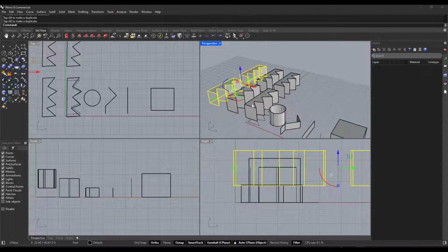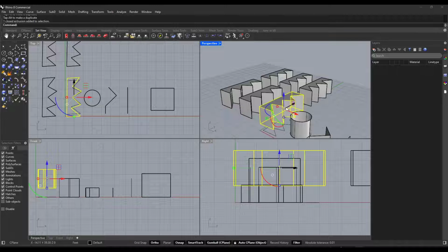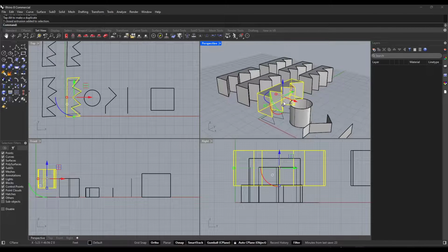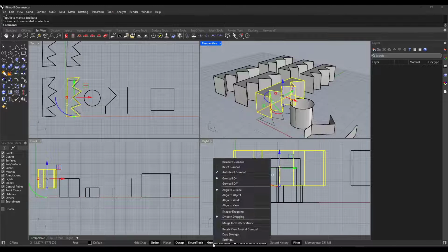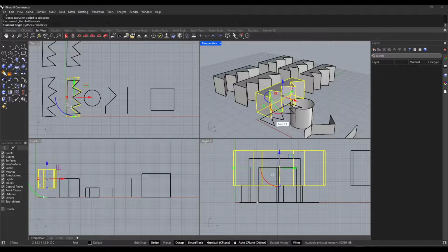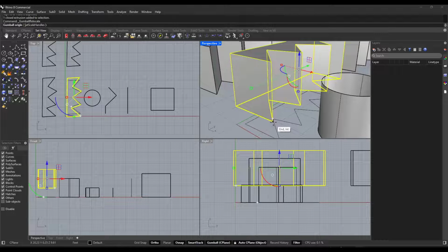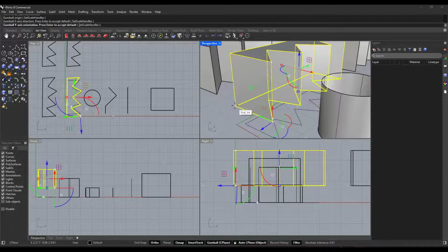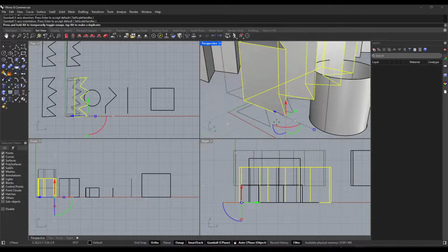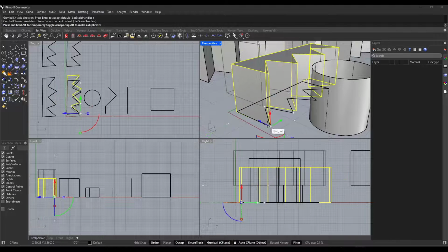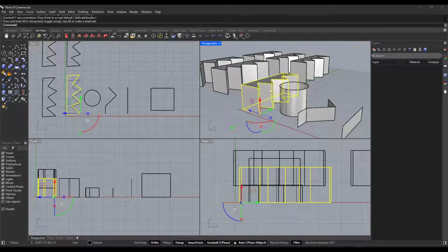And so sometimes, now there is the option in here to relocate the gumball. So if I was to scroll in on this thing a little bit, and we're just going to right click on the gumball option and click on the option to relocate, what you can do is pick a point, right? So maybe this point right here, and you can set the direction that the gumball is supposed to face. But notice how that's going to relocate that gumball to this corner point right here. And then you can click and drag that point in order to snap it to different things. So you can move it so that it's at a different point on the object right here.